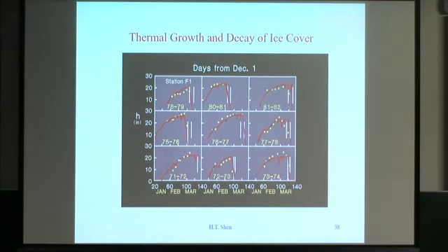If we look at the thickness variation over the winter, you can see it's pretty much like this. This is on the St. Lawrence, it's well managed, so we don't have a mechanical breakup. If we have breakup at this time, we will most likely get an ice jam. If we get breakup over this period, that is thermal meltout. That means we need ice mass.